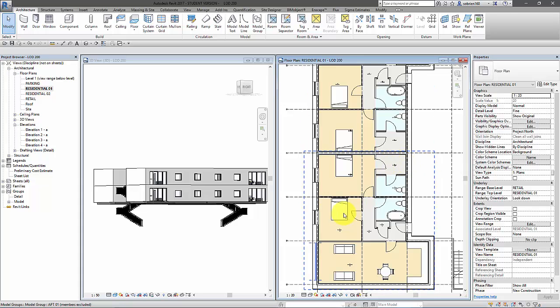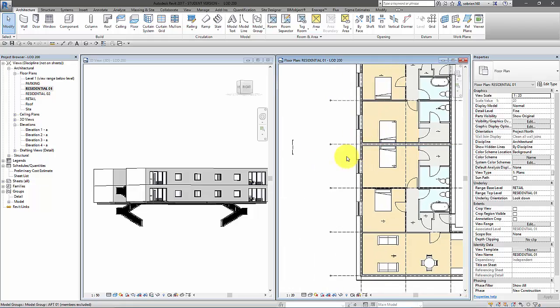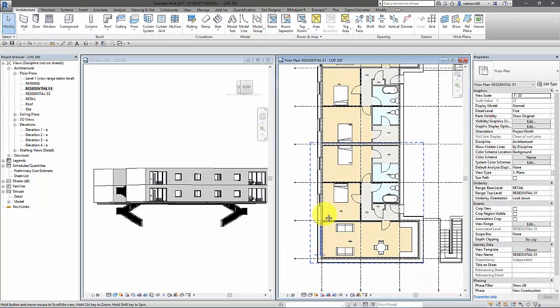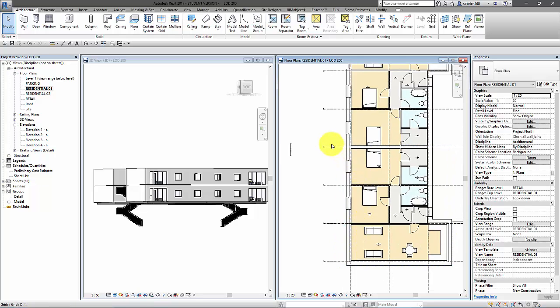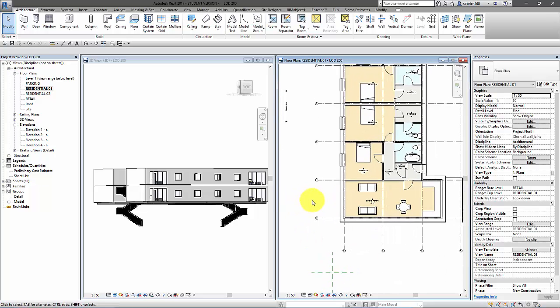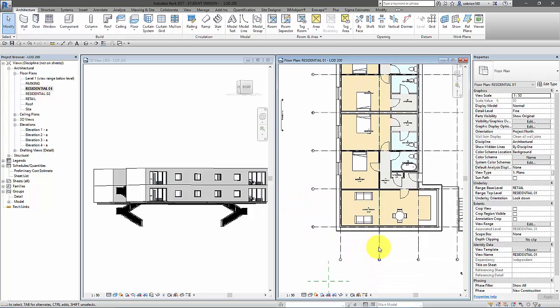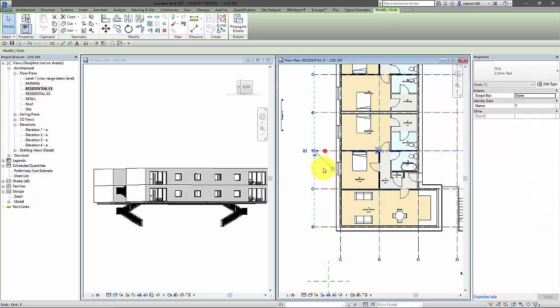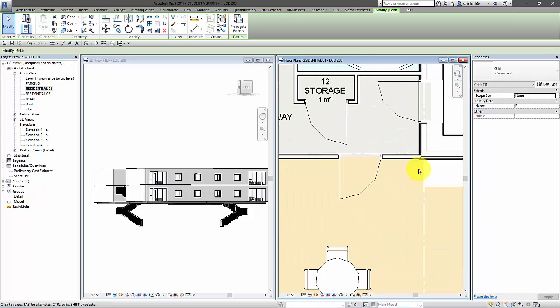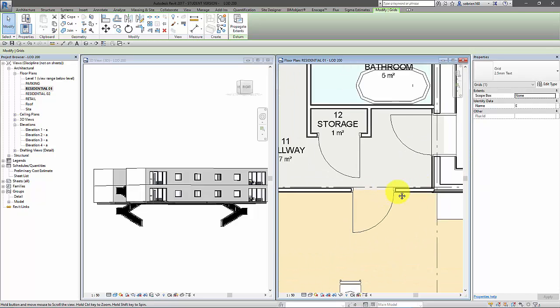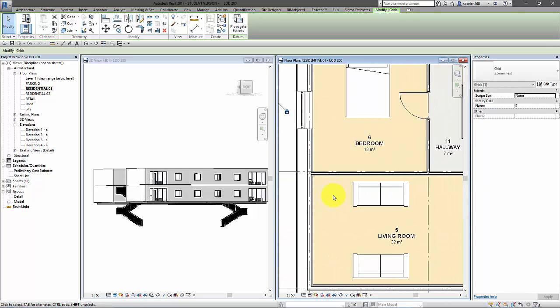Of course, you have an idea as to how the grid of the apartments sits on top of the parking grid if you have a parking grid. But the most important thing is to get the main structural elements correct here. We could probably divide this out afterwards where only the main structural grids are showing. So you could say, for example, that we don't necessarily need this element here because it's not structural. We could delete this one, and we could probably delete this one and this one as well. So we would have this one, and then these two, which are running through the main core structural walls. So then we have the main primary structural grid.